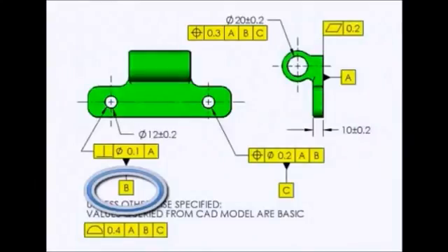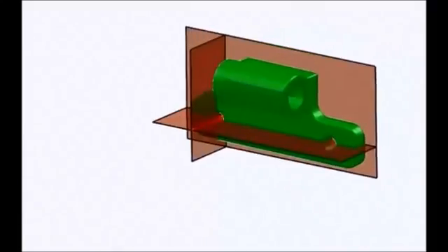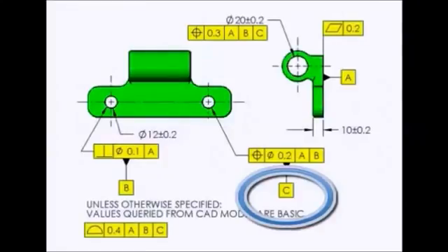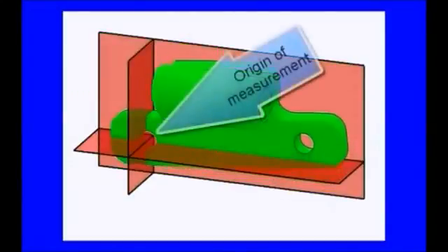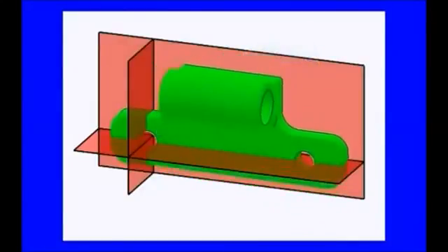Then we would select another feature such as one of the holes as datum feature B. We would then use the axis of the related actual mating envelope of that feature and align to that. Now that is actually the intersection of 2 more planes that are at right angles to the first one and to each other. Now we use datum feature C to orient those planes because we have an origin, but the part can still rotate. The axis at B only took away 2 of the degrees of freedom, so C takes away that last degree of freedom for us.